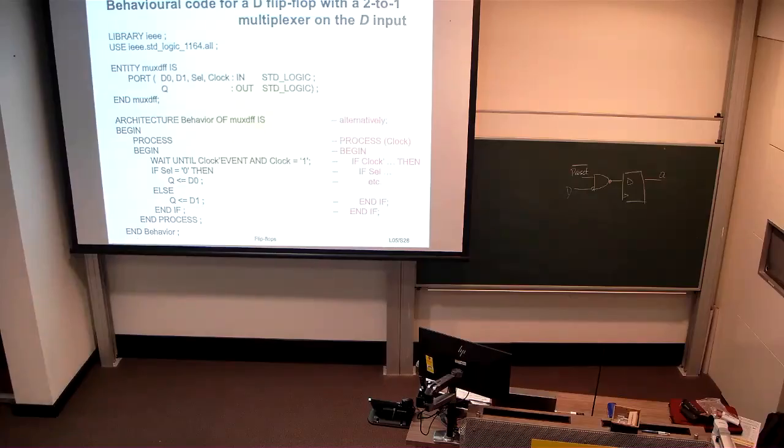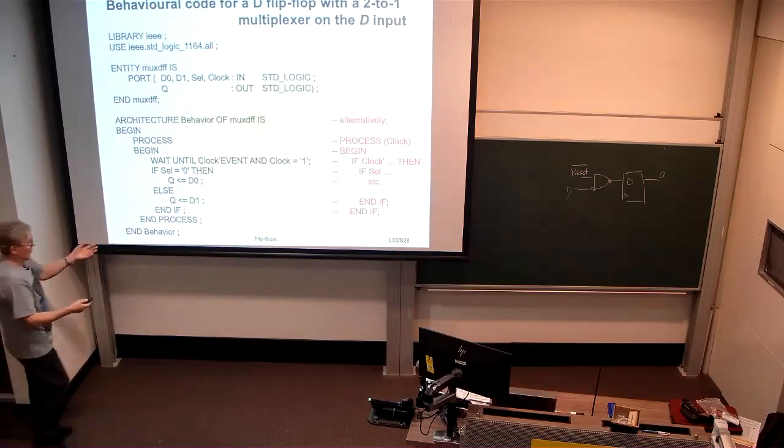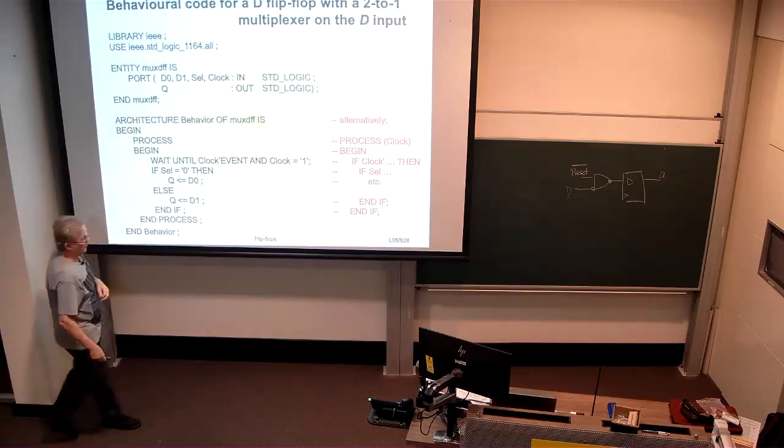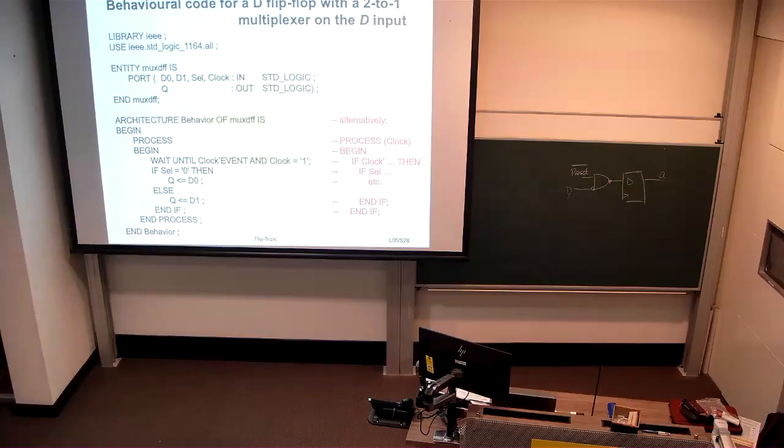mux DFF. Now it could have also used the if clock tick event and clock equal 1 semantic and had the mux subservient to that. That's equivalent in terms of what would be synthesized.